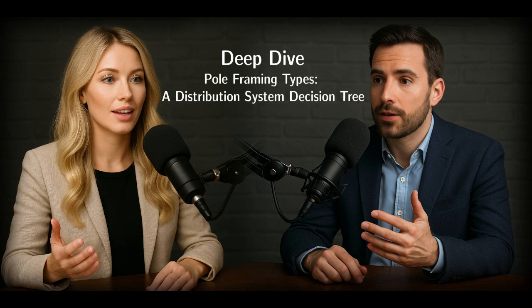It's the most common type of through construction where conductors just pass continuously and relatively straight from one span to the next. Gotcha. So in these cases, you'll see pretty standard pole strength, probably minimal specialized hardware. And the conductors are typically just tied on top of pin or post insulators, or maybe simply suspended straight through on suspension insulators if it's higher voltage or a longer span. It's the most economical and the most common configuration. Designed for normal operating conditions with minimal structural loads beyond just basic suspension.